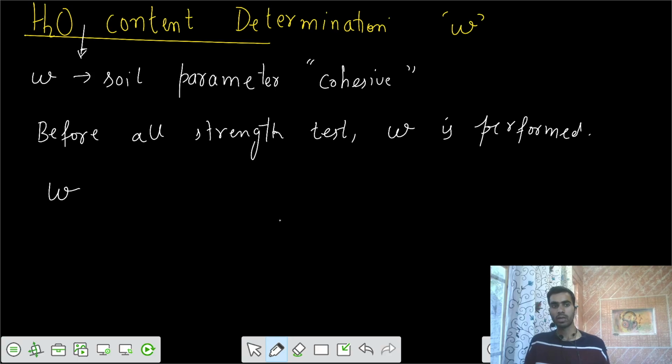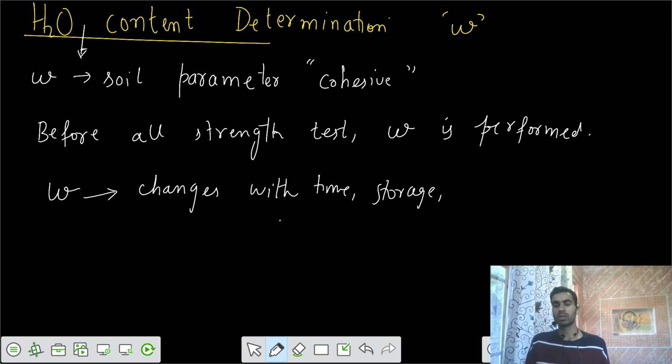We say that water content changes with storage, it changes with transportation, changes with time. So this becomes important: before you have any strength value of soil, we should say at what water content this value was achieved. So storage, transportation, it's going to change with these conditions.